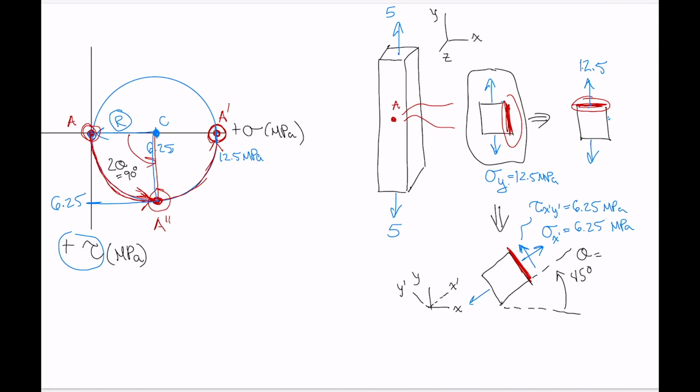And then we know we have to have another normal stress there and another shear stress there, with matching shear stresses like that. Now what I've just drawn isn't a complete description of the stress state on that element, because we're missing the normal stress on these other two sides.